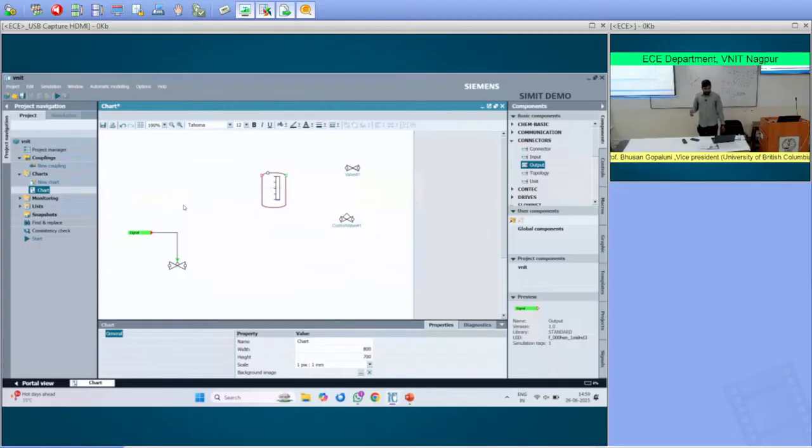So here we can simulate everything, but if you want to change the valve characteristics, like normally open, so that when there is a power cut it will be open, all those parameters we can't do in this. That will be done in CTE only. Basic parameters we can test in this even without CTE, without importing from COMOS P&IDs. For all the basics we want to train, if you want to do basic testing, that is also possible in this SIMIT.